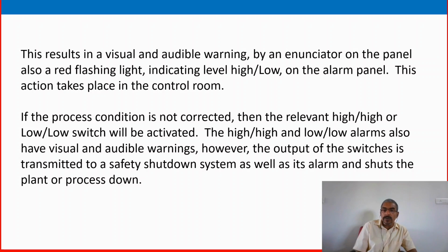However, the difference is the output of the switch. The output of the switch is transmitted not only to the alarm or annunciator panel, it is also transmitted to a safety shutdown system, so as well as the alarm, it shuts the plant or process down.